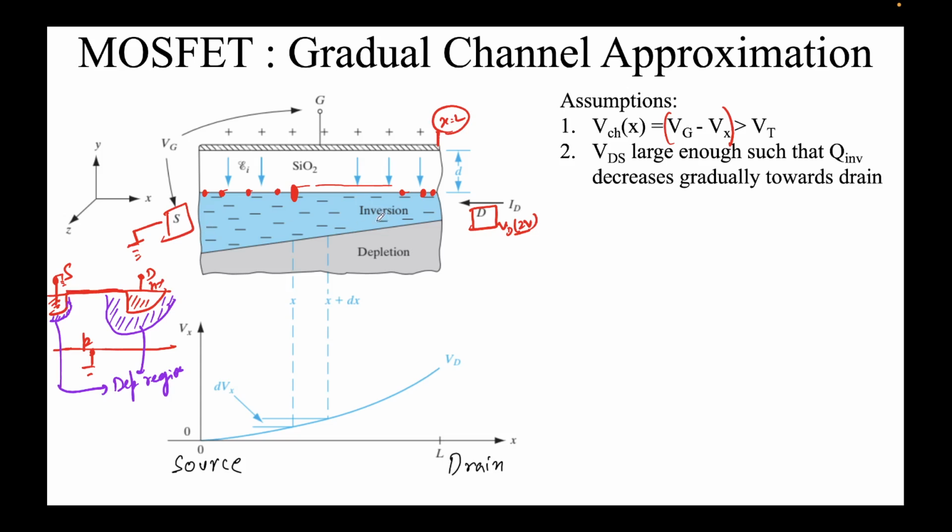And the primary reason this arises is that the depletion regions between the source and substrate and the drain and substrate are different. So there is more of the depletion region on the drain side. That's why it looks like this. But inversion is still happening on the drain side as well. So inversion is happening throughout. It's just that the extent of inversion charge is smaller on the drain side.